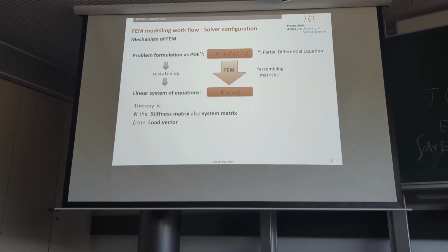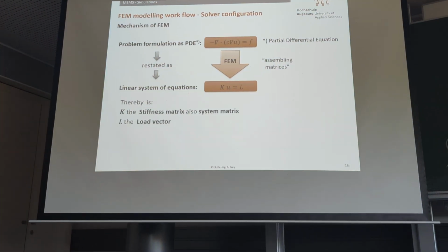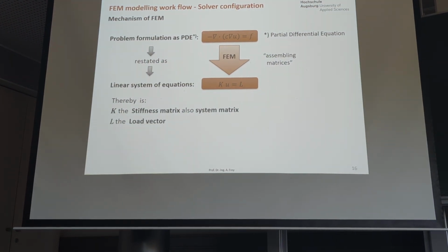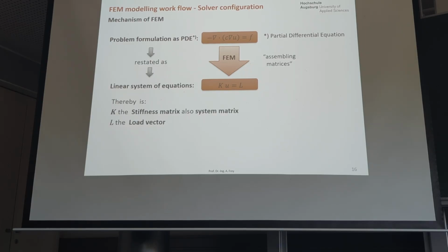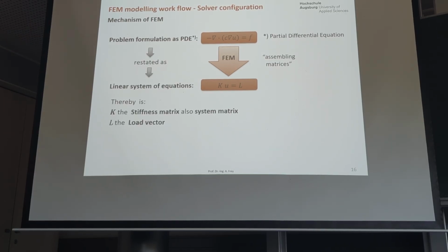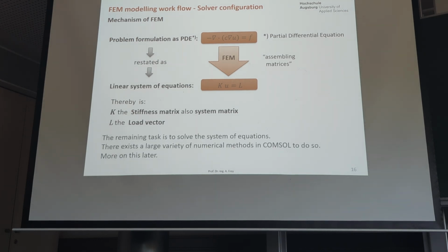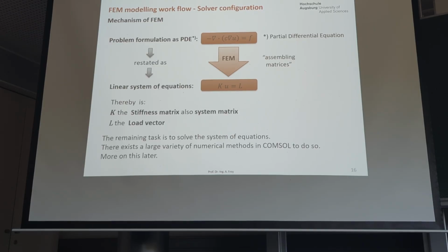The tendency I observe, and I probably did myself when I was a beginner, is that people try to do everything in the first run: make a complicated geometry and include every possible detail of physics, and then in many cases something goes wrong, and then it's difficult to find the problem. So it's better to start very simple. 2D is one of the key concepts, and then you later make it more complicated. Here I just put in a short statement what I lengthily explained minutes ago.